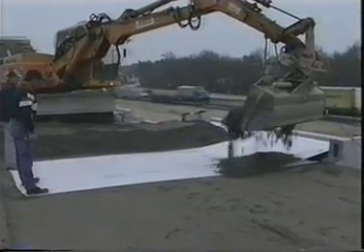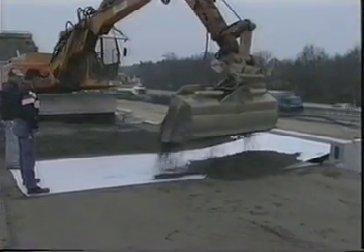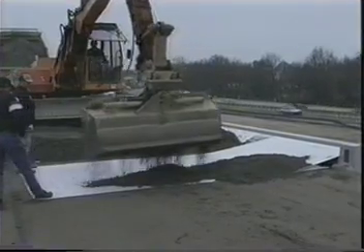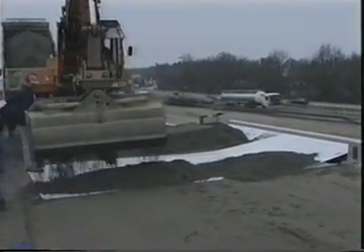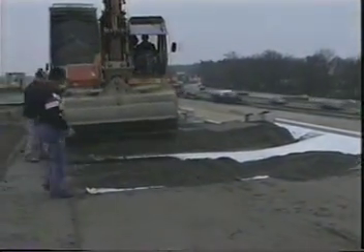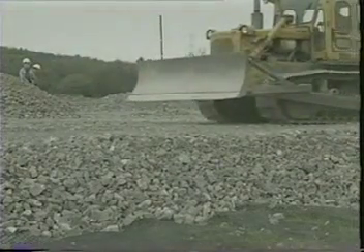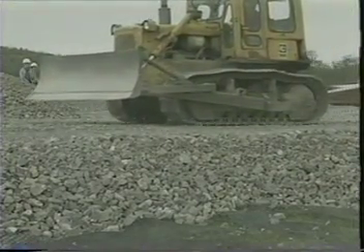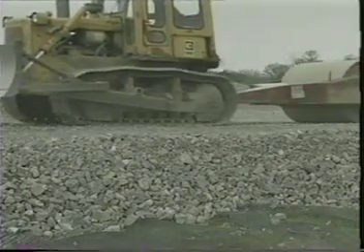The ultimate unit shear stress that can be developed between the fill and the reinforcement is related to the φ value of the fill and the surface roughness of the reinforcement material. Simply put, the better the grade of fill and the rougher the reinforcement, the higher will be the unit shear stress generated between reinforcement and fill.